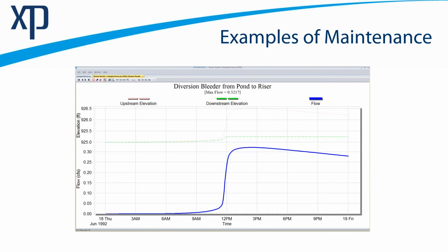Another was the weir. The hydraulic computation does not solve for the velocity of a weir. In previous versions, the velocity would show, but it would be 0 all the time. And so that's somewhat misleading, right? There wasn't a 0 velocity. We just didn't compute it. And so now when you go to the review results or the time series graphing for a weir, we totally suppress the velocity.